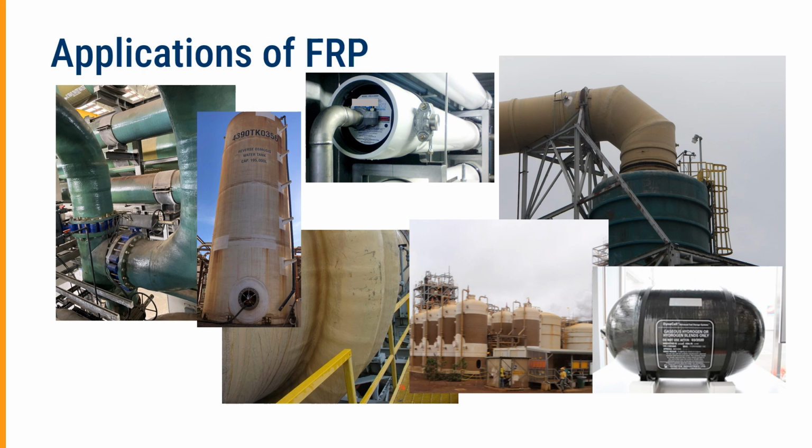Some applications of FRP, and in fact, a fairly broad look here from an industrial perspective. We have piping in this slide, a fairly conventional storage tank with, in fact, an atmospheric overflow. This is ducting. These, in fact, are expansion joints made out of FRP. This is a pressure vessel for reverse osmosis purification of water, industrial scrubbing and ducting equipment. These are a set of industrial reactors.